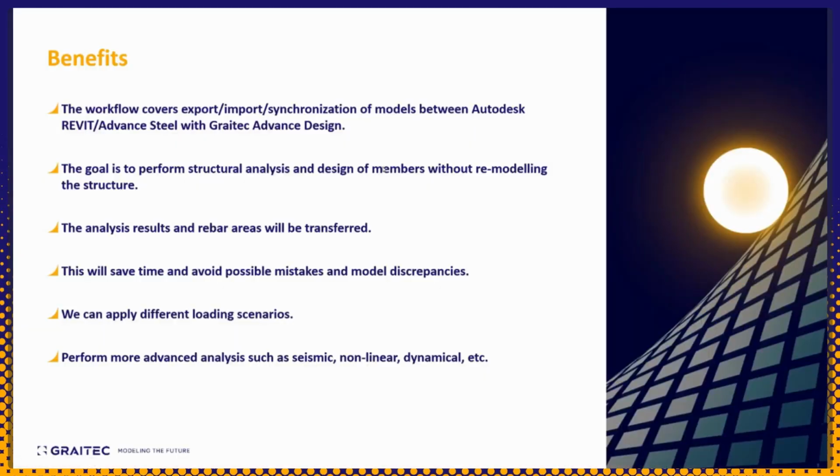Okay, so let's talk about the benefits of this workflow, which is going to be helping you basically to send your models from Revit or even Advanced Steel inside Advanced Design to perform your analysis. As you see here, the workflow covers both export, import, and synchronization of models between Revit and Advanced Design. The goal is to perform the structural analysis and design of members without, again, remodeling the structure in your structural analysis solution, in this case, Advanced Design.